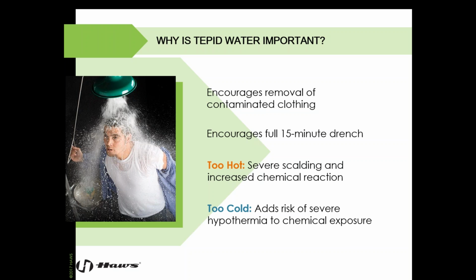It encourages the full 15-minute drench, as Brian mentioned. If the water is too hot, over 100 degrees Fahrenheit, you could risk severe scalding and increase the chemical reaction. With hot water, as you may know, the pores are opened more and the chemicals could get into your pores. If the water is too cold, that's going to add the risk of severe hypothermia to the already occurring chemical exposure. A lot of people with tepid water think it's only needed for cold regions. So tempering for hot water in hot climates is often overlooked, but it's definitely a necessity in certain regions throughout the world.